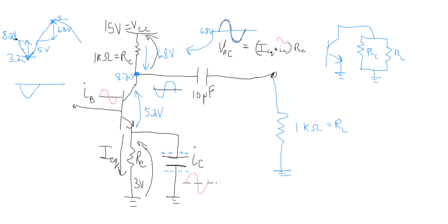The key to understanding this is realizing that when you are stopping current, you are raising the voltage barrier where the current would have entered. So in the same way, when we want to draw current, we drop the voltage barrier, we lower our voltage to create a sink. In this case, we're going to push back against the voltage by increasing the voltage level at the collector of the transistor, right here where the 8.2 is. So we're going to rise above 8.2. Now, in the no load situation, we went all the way up to VCC. We rose to 15 volts.